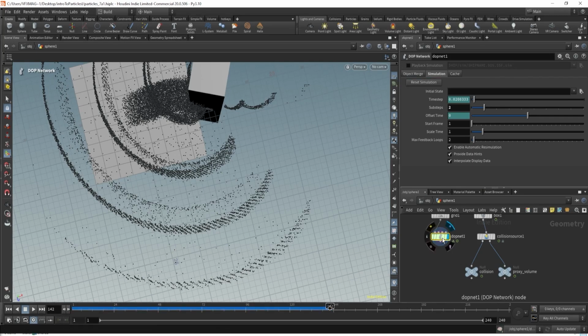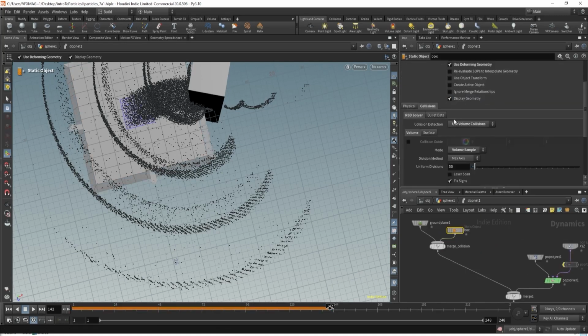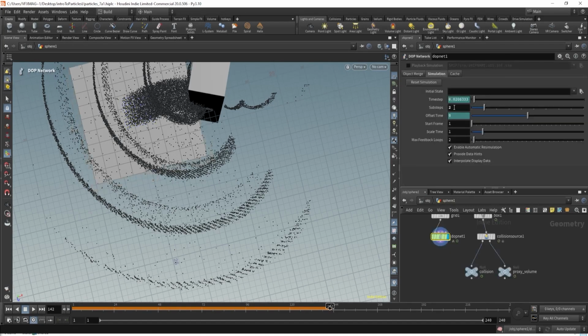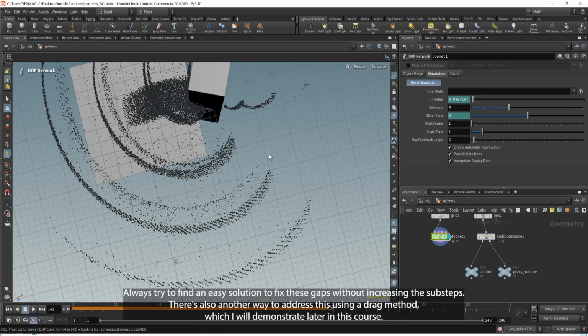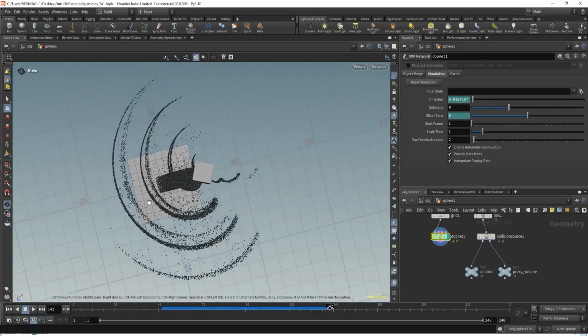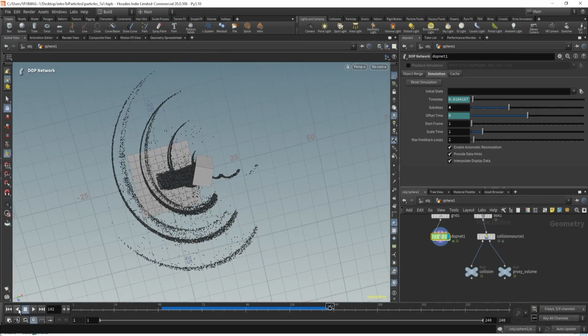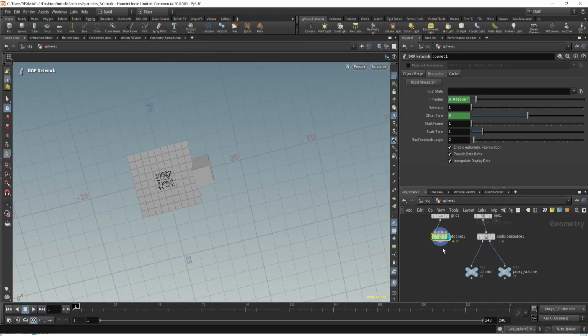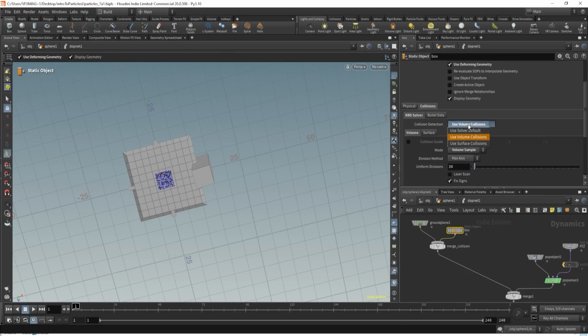Yep. So yep, I will recommend you to check all the steps and everything, and you can just increase this to 4, so it will fix it. Yeah. So whenever you increase substeps, it will increase simulation time also. Yeah. So now it's fixed. Cool. Let me reset everything now. And we understood this volume and difference between volume and surface. You can utilize in some cases, and you can utilize this also in those heavy geometry cases.